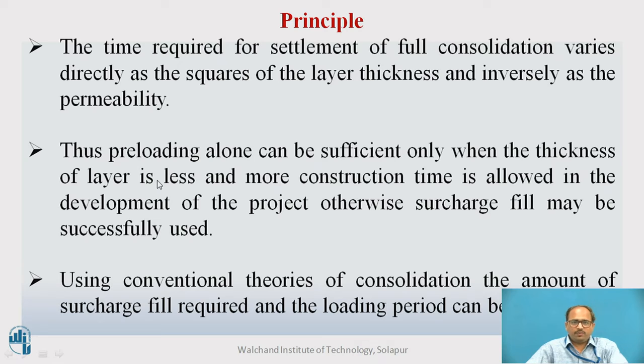It is only possible when your soil layer thickness is very small. Very small means you can take only 0.5 meter or 1.2 meter. At that time it is possible to apply the preloading technique here, and when more construction time is allowed in the development of the project. Otherwise, surcharge fill may be successfully used.